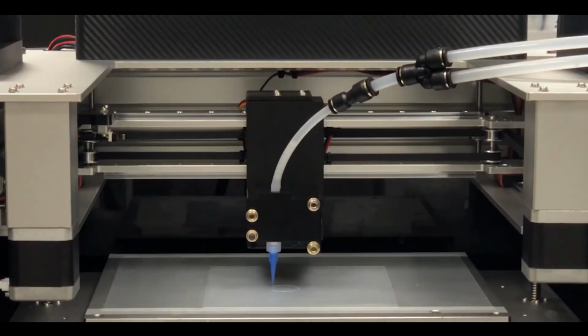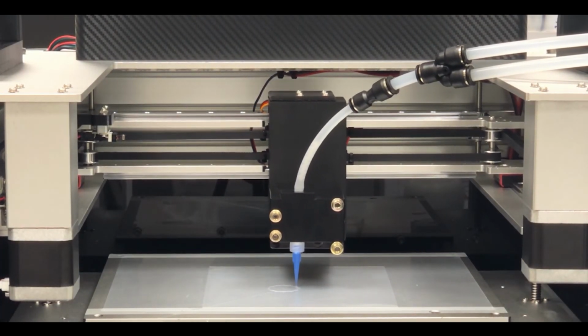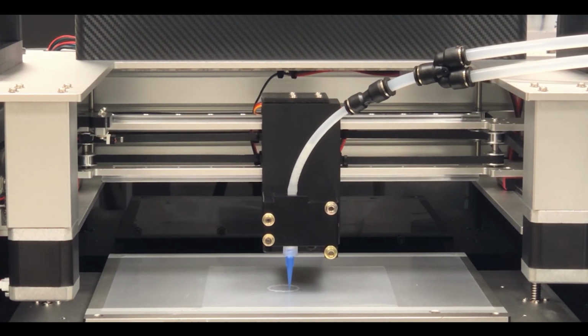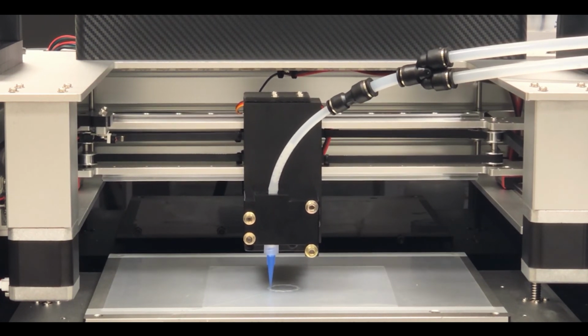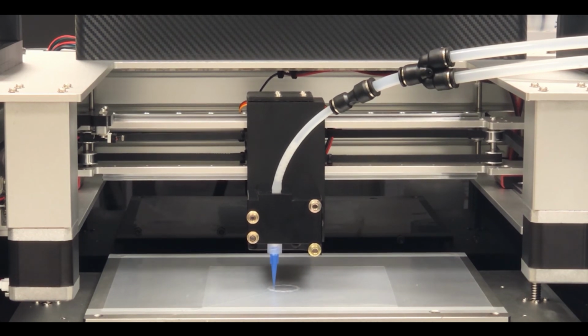It is important to make sure that both E and I are selected under extruder block, and then wait for the material to be extruded from the nozzle. When the material is extruded, if the extruded silicone shows a steady straight line and the nozzle is not blocked, then as long as the material flow is sufficient, you can start to print.